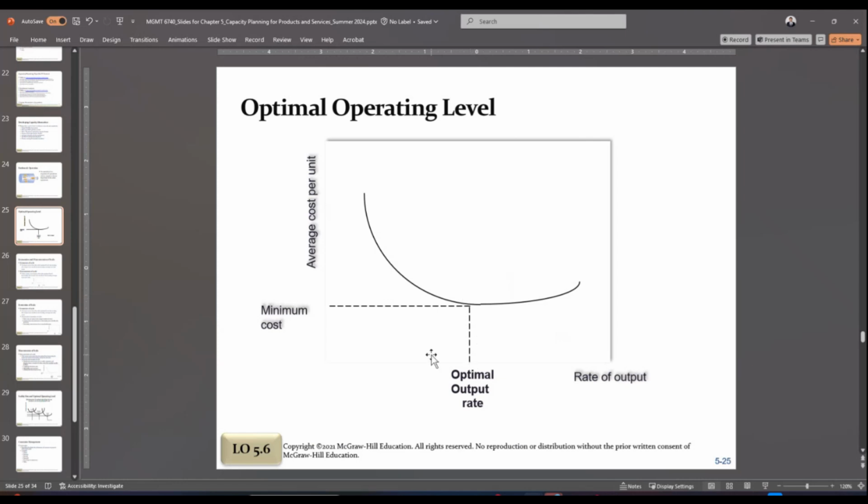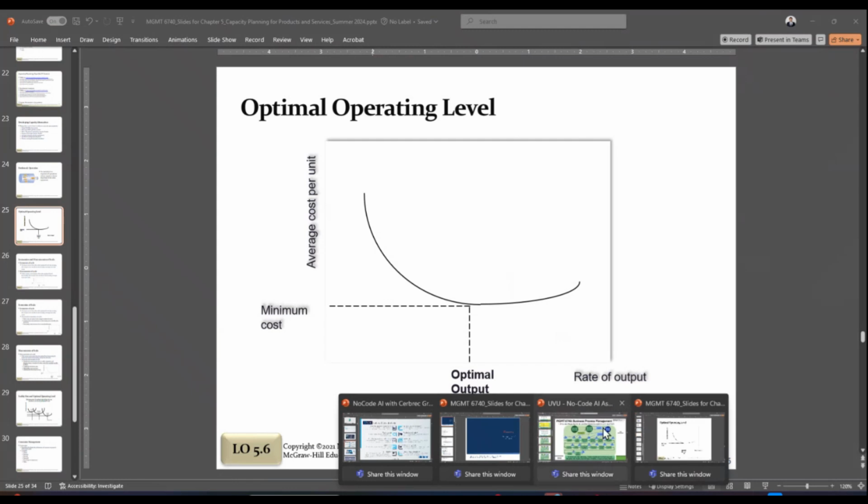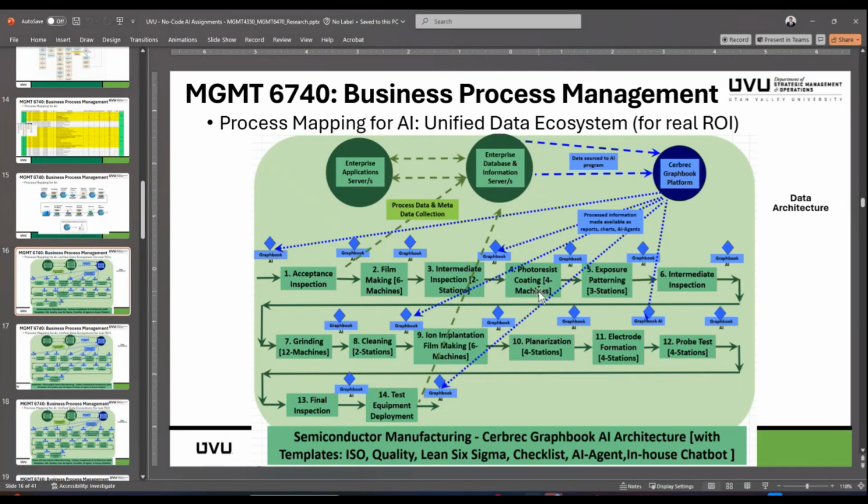And again, the reasons are, for manufacturing any component or delivering any service, there is a setup cost, there is an equipment cost that you have already invested, and you are factoring it over a longer time. So as the quantities increase, suppose I have this process, photoresist coating, and each has 4 machines. I have paid for that machine, and there are raw materials that I have paid for. Then there are operators who are paid on an hourly basis, and there is some special setup required.